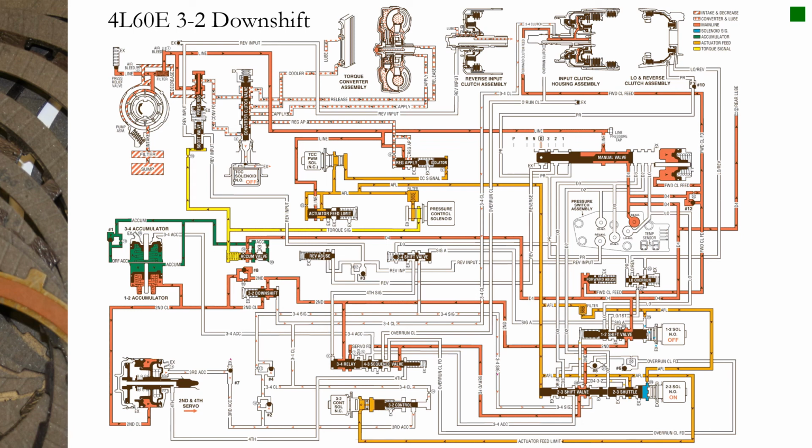That 3-2 downshift when I'm coasting is going to be completely different than when I'm cruising at 45 miles an hour on a 2-lane road, I have to pass somebody, and I stomp on the throttle and it downshifts from 3rd to 2nd. Now I'm doing this under load and forcing the engine speed up, as opposed to a coasting downshift where I'm just letting it drop down into gears and I'm not intending on raising the engine speed and delivering torque.